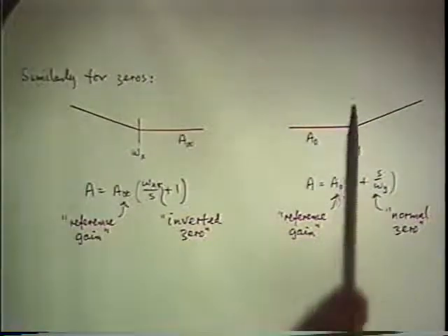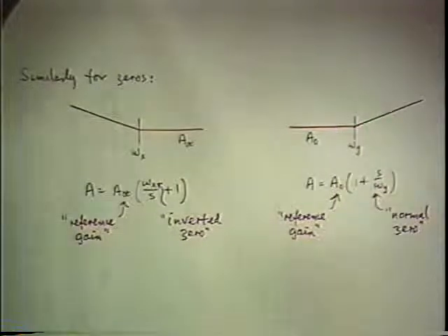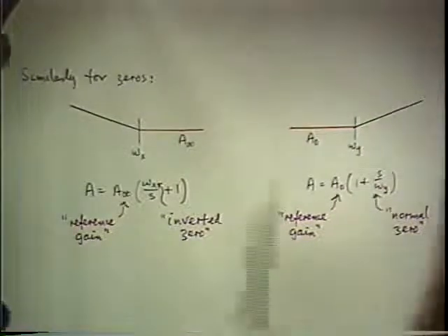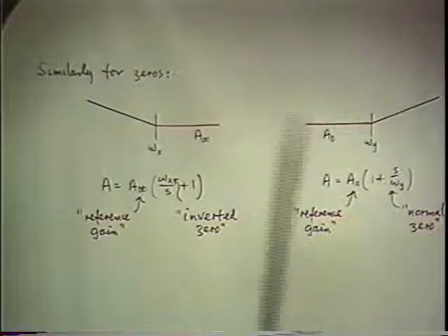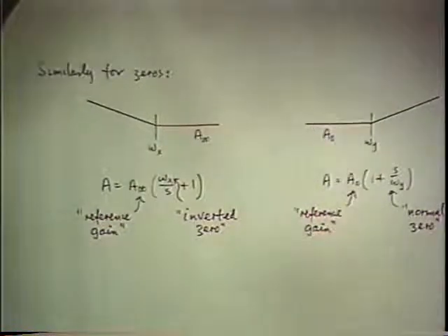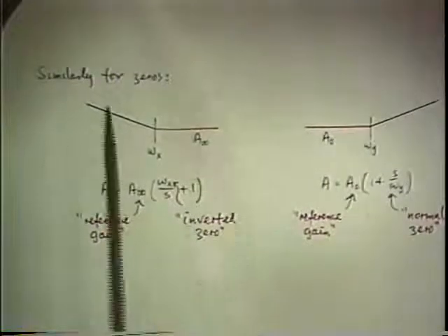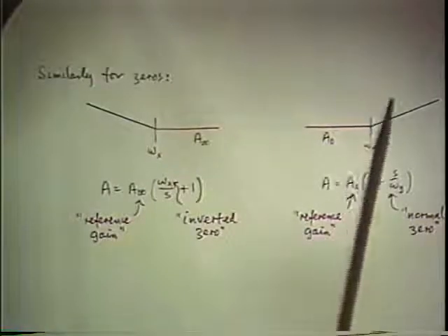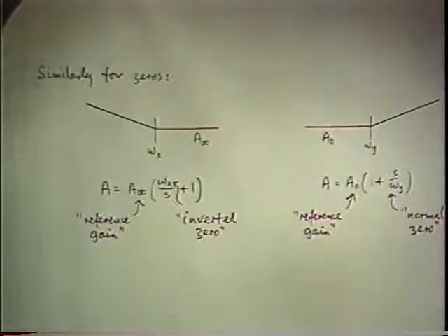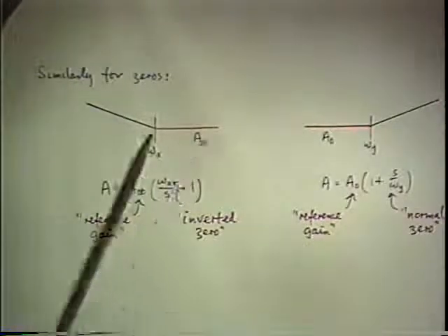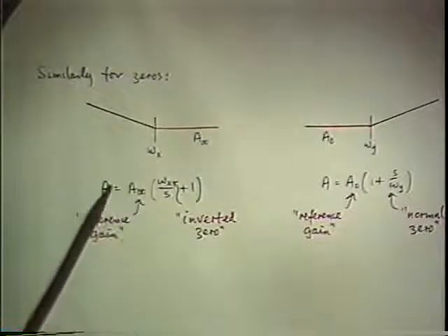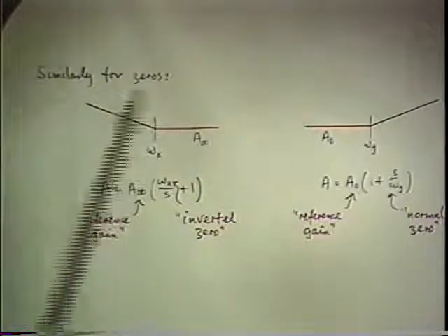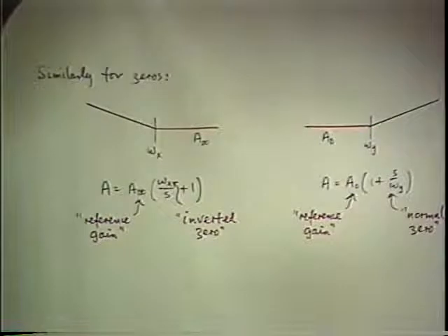All of the detailed geometry of the 3dB smooth curve simply carries along with it. You don't have to redraw it. Now you see the symmetry between vertical inversions, which you know about already. The horizontal inversion works just the same because it's also a logarithmic scale. And so a horizontal reversal of a normal zero gives you an inverted zero. And again, the reason that's useful is it allows you to retain the flat gain as the leading coefficient, the reference gain, which is obviously the most important part of the characteristic. Same argument as before, just completes the entire symmetry.